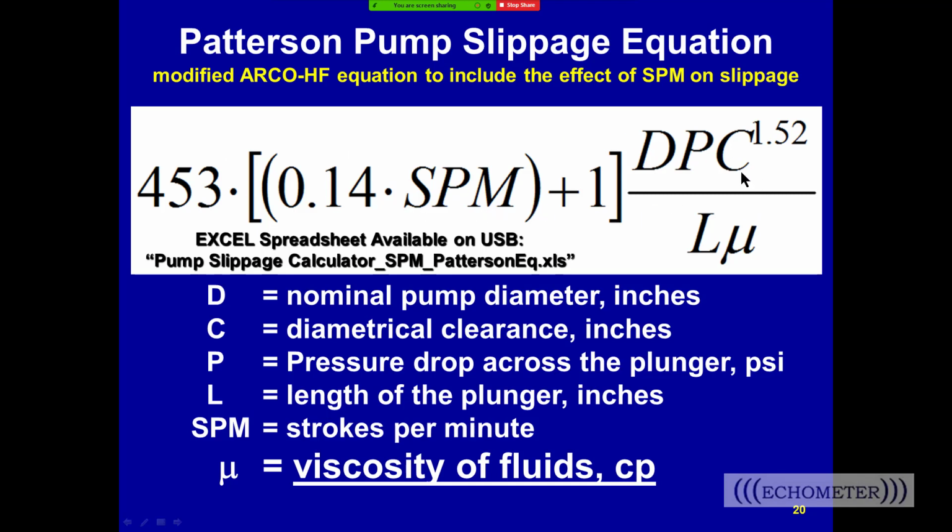But it's averaged over the entire stroke, which is how we measure the data. Whereas a Bernoulli equation would calculate over each section, when you're picking up the fluid load, carrying the fluid load, compressing the fluids, it would handle all those conditions. So, long term, we may end up using the Bernoulli equation, but right now this equation works great, and we don't really know the limitations on the viscosity.